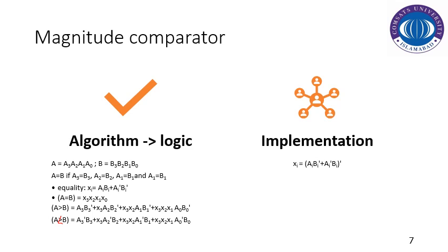As far as the implementation is concerned, I've mentioned that due to some irregularities in the circuit, we have frequent use of the comparisons in terms of the exclusive OR operation, that is x3, x2, x1 and x0. In terms of implementation, we can use either the exclusive NOR gates or the exclusive OR gates.